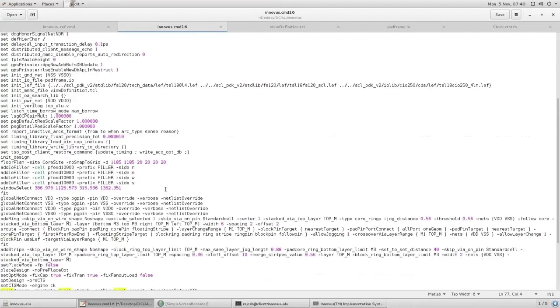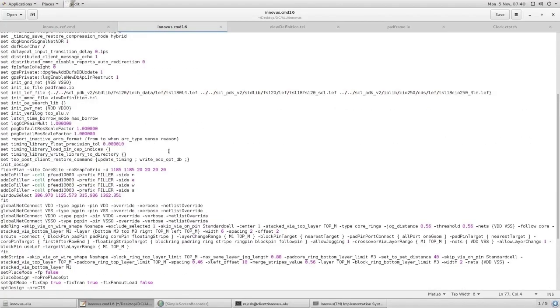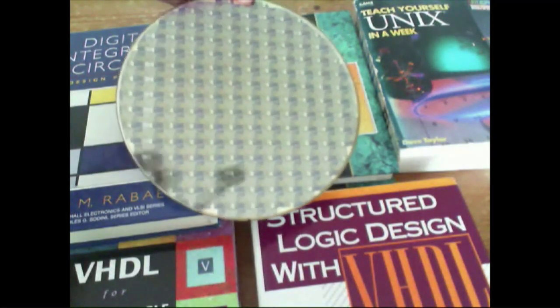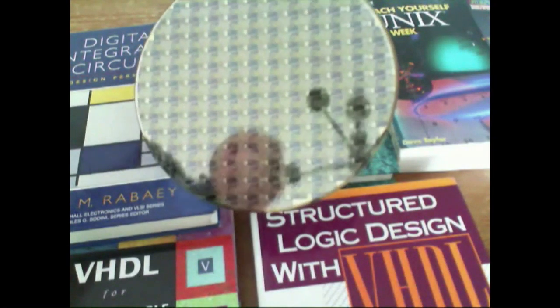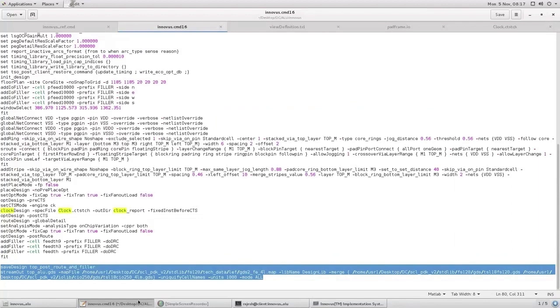The simulated annealing placement program now has the capability of performing low temperature simulated annealing, LTSA. So LTSA determines the temperature at which an existing placement is in equilibrium and starts cooling from that temperature, thus effecting local improvements to a placement without disrupting the global placement characteristics.